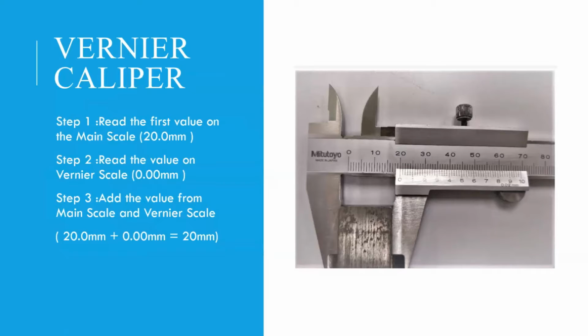So, the instrument that they talk about is vernier caliper. Step 1, to read the vernier caliper, we need to read the value on the main scale, which is this one, 20 mm. Next, we take the reading on the vernier scale, which is this one, that is aligned to the main scale line.